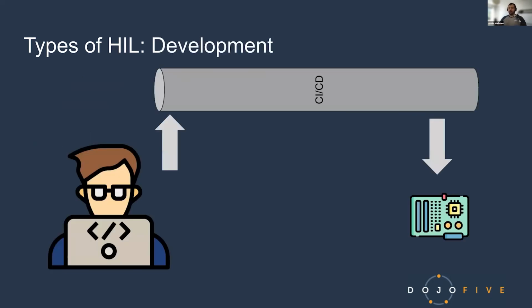A lot of times you have HIL setups for development. So again, you don't want to test all your requirements on your hardware, and especially you don't want to test previous requirements of your hardware, right? Because in order to make sure that you didn't break anything, you need to actually test it on hardware. And there are basically two ways to do this. You either do it after each push or after each merge, which will be really painful, or you wait a while and then you test it like once every 6 months or once every month or whatever.